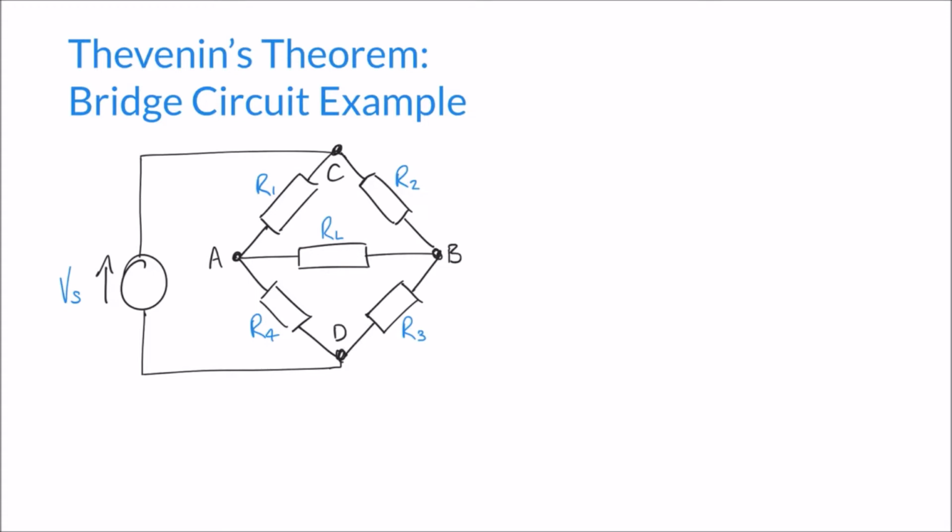So often when we're investigating the values of unknown components, like I mentioned earlier, let's say R3 is our unknown resistor, but we know the values of R1, R2, and let's say R4 is a variable resistor, we can adjust R4 until we get no current or measure no voltage across the points A and B. If that's the case, then our bridge circuit is balanced, and it's a series of simple calculations to then calculate the value of our unknown resistor.